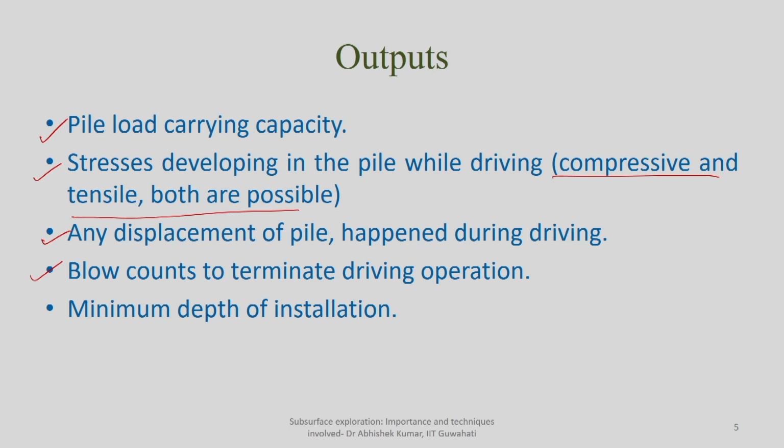Then this is a very important thing, how many blows will be considered as an installation guideline in order to terminate further driving of the pile. Otherwise, the pile will not go further into the soil, rather there will be crushing of the material. So, that blow count termination guideline can also be obtained based on these in situ tests. Then the minimum depth of installation, taking into account how much resistance the particular pile has to offer against the external loading, can also be determined here.